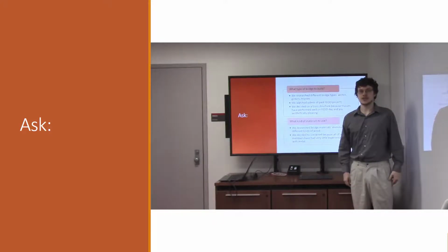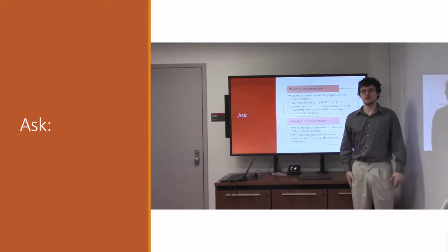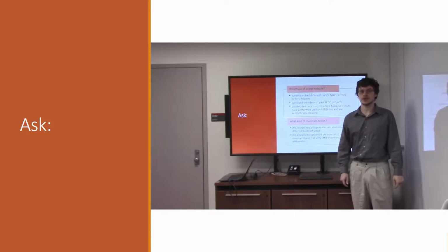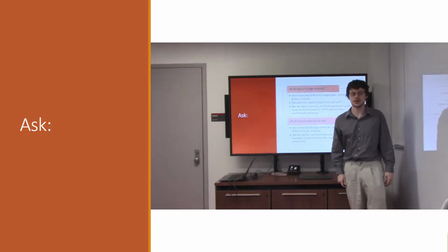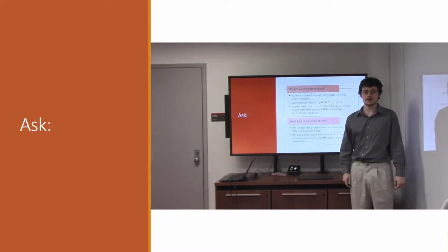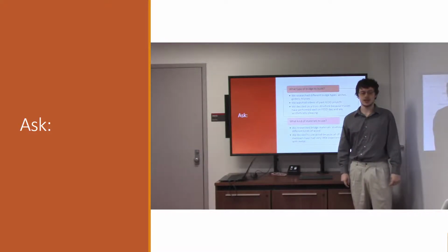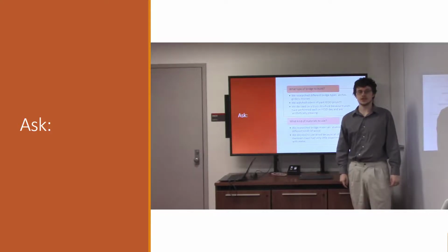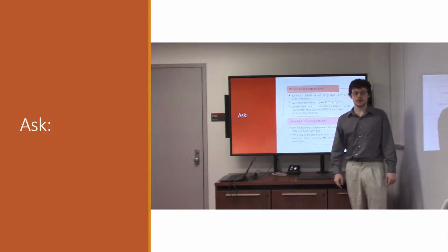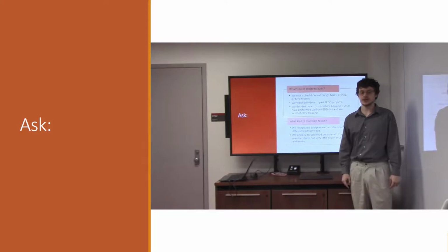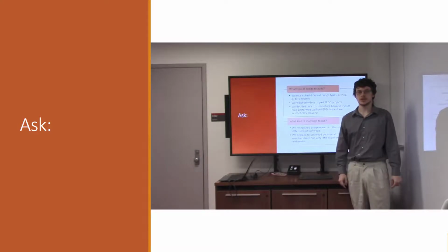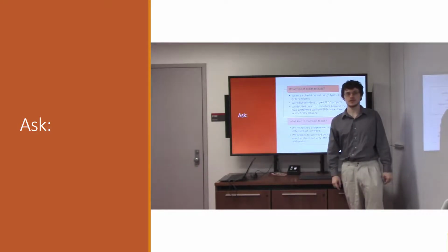The second question we asked was what to build the bridge with. We looked at two main types of materials, aluminum and wood. Aluminum is strong and light, but difficult to work with, and none of us had experience with metalworking. So we decided on wood. Wood is also strong and light, and was relatively easy to build with. We used pine wood because its strength to weight ratio is high enough to fit the parameters of the project and it was cheap enough to be well within the budget.